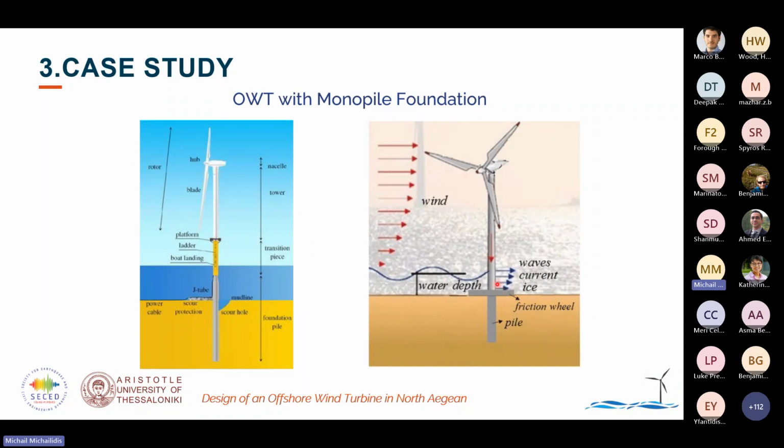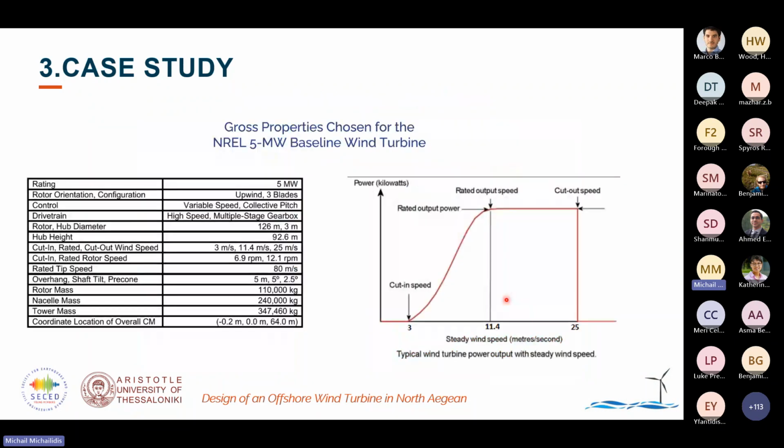The loads that we should account for in this design are the wind profile that follows an exponential distribution, hydrodynamic loads and hydrostatic loads as well, currents, waves, ice, and of course seismic if being in a susceptible environment.